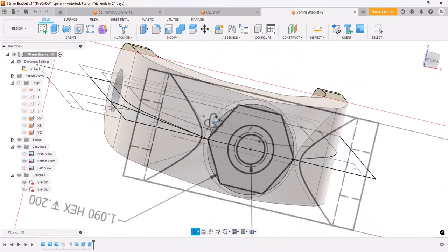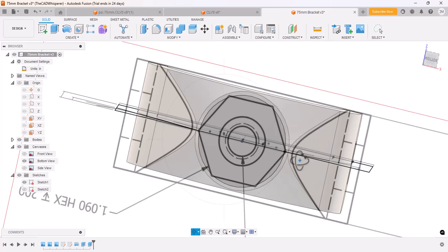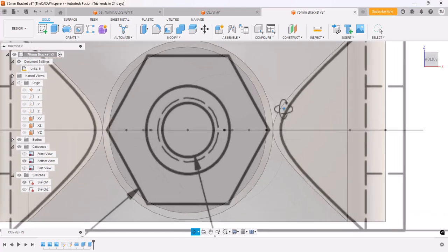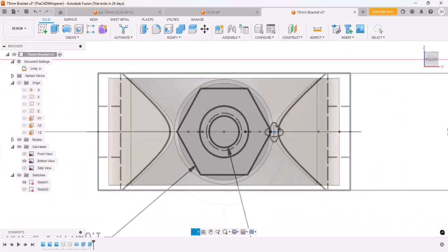And let's go ahead and do that. And also we can see that arc on the canvas. Now we could adjust that a little bit, and that's what I was saying earlier. I might come down with that angled line that we put in, put it at the radius of that fillet. We haven't put that fillet in yet, but that might get us closer to matching the original geometry.